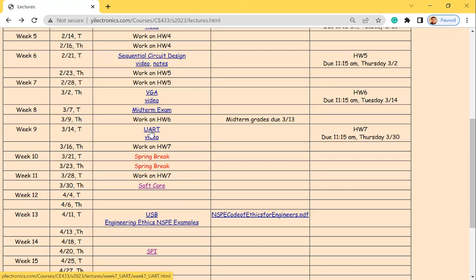When you are dealing with microcontrollers, you hope the microcontroller has SPI, has I2C. That's the Arduino Uno. But if you need 2 SPIs or more UART ports, the Uno couldn't even do it. You have to use the Arduino Mega, which has more pins on it, and they have RX1, TX1, RX2, TX2. They have 2 UART modules in it. I think our Artix-7 FPGA chip has a lot of pins compared to the Arduino Uno chip you have used.